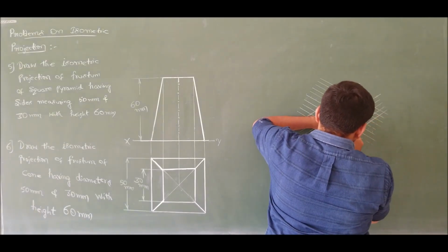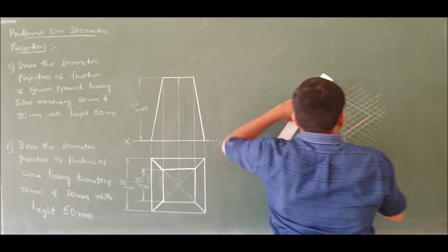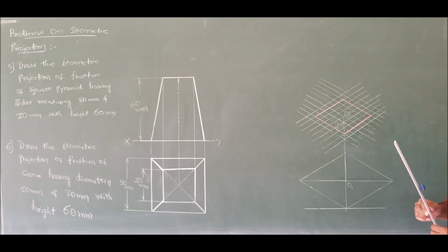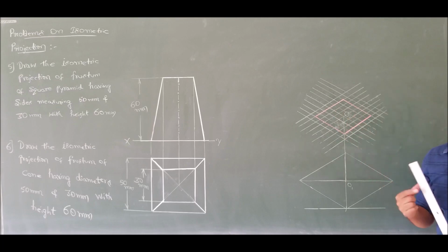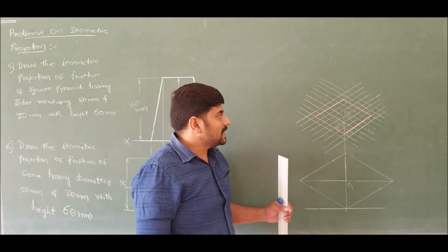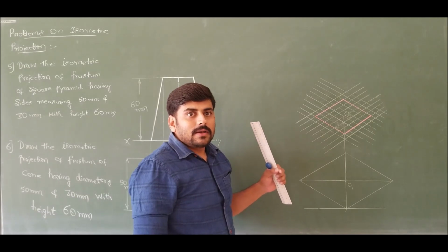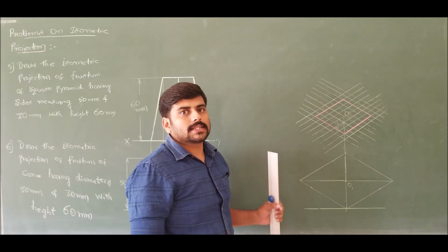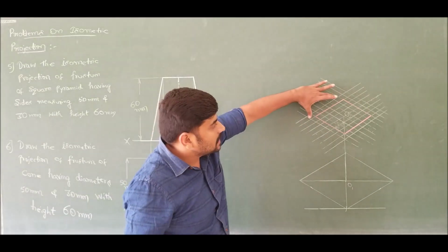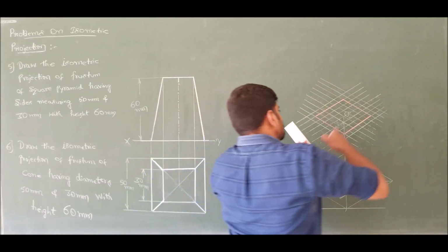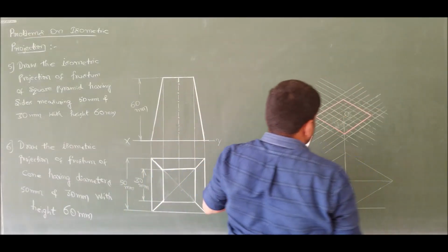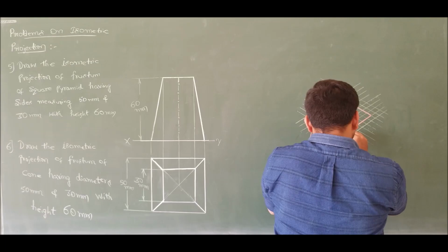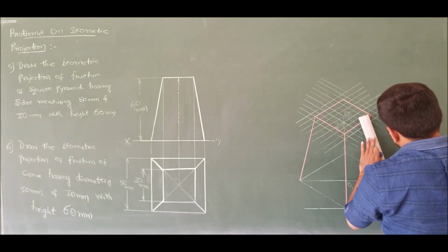This completes the isometric projection of square of side 30 mm cross 30 mm in iso sheet, which is nothing but 3 boxes cross 3 boxes. Now through the visual inspection, dark the visible bottom face edges and also top face edges and also the longer edges. So through the visual inspection, it is clear that the top face is completely visible. So dark the top face and also the longer edges which are visible: longer edge 1, longer edge number 2 and the longer edge number 3.